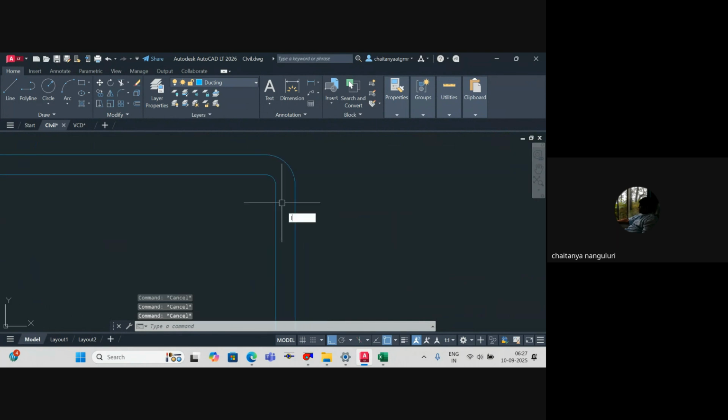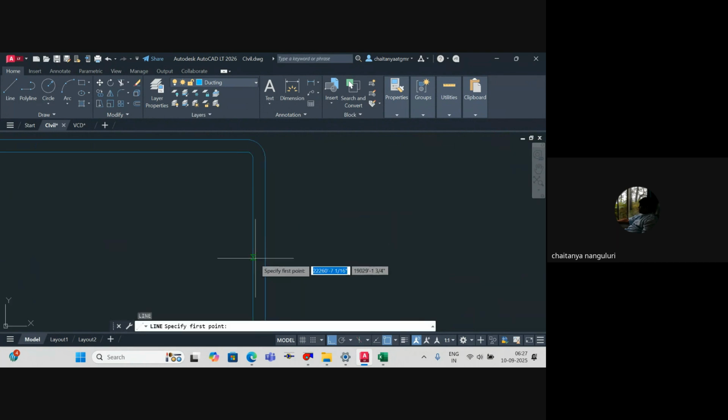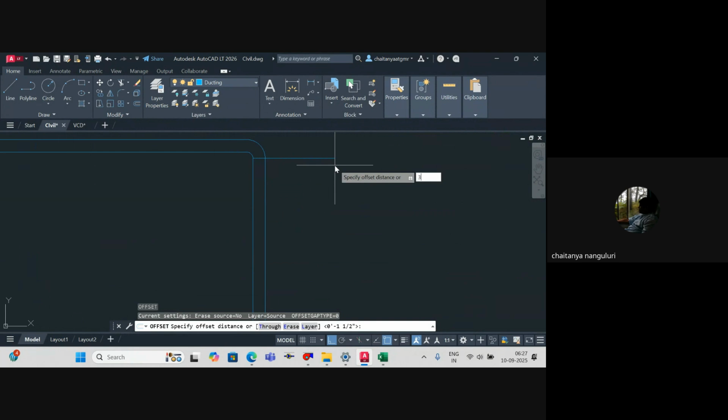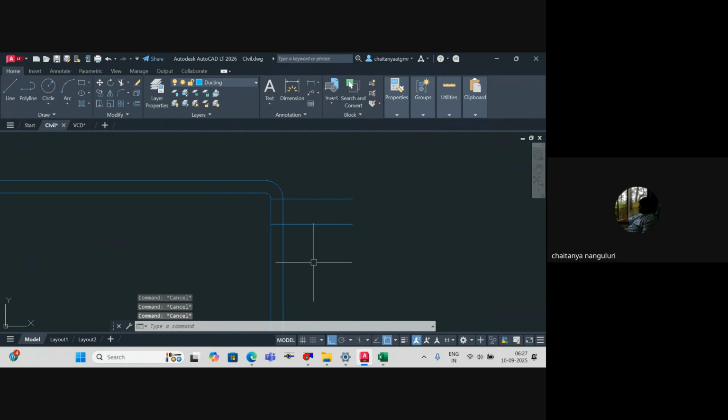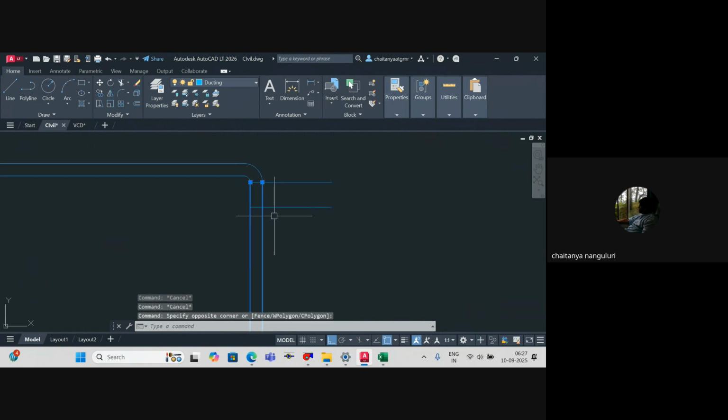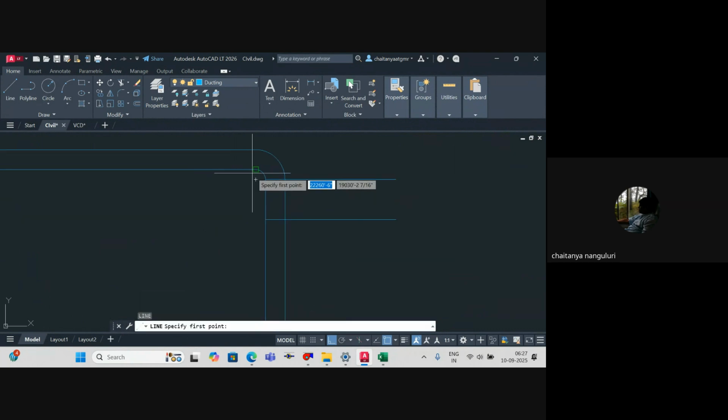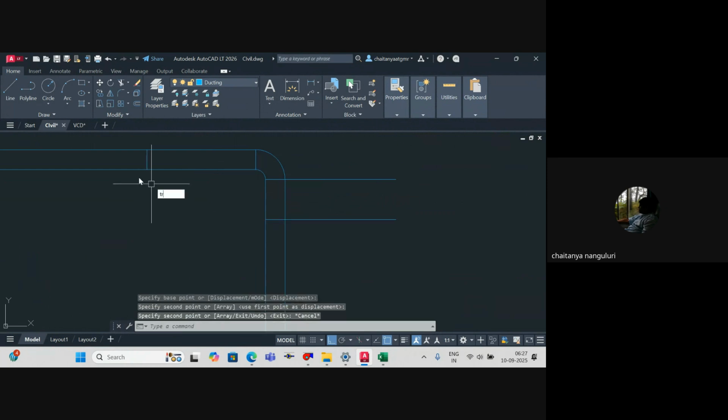And then let's say this is your height. Let's say the static pressure of the fan is, for example, 2 inches. You can take even 3 inches to be safer. So 3 inches, you'll take it over here. So this is the minimum height that you have to maintain on the upward scale. Similarly, just a second, copy.